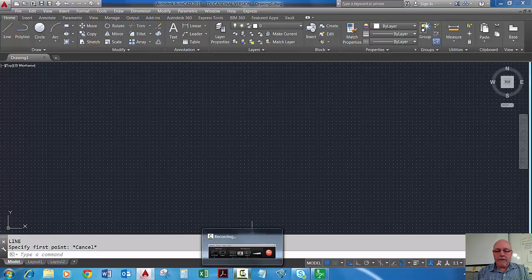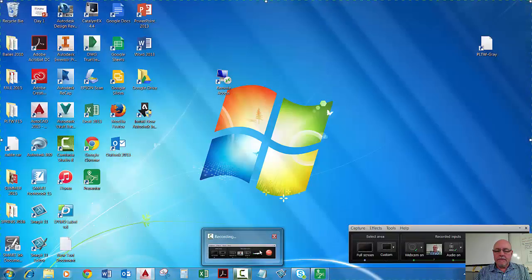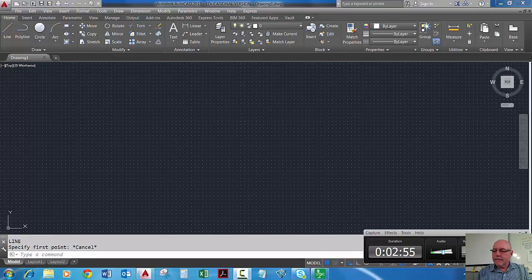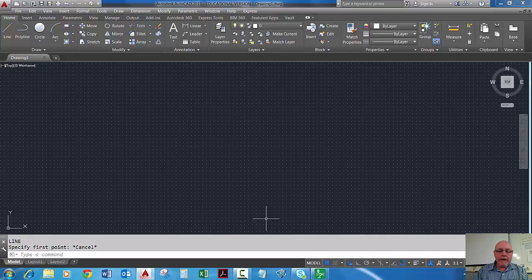I'm going to pause for just a moment. So you'll find the use of the dynamic input pretty handy. The book will take you through several steps, so follow those. Essentially, I'll just show you in using it. Don't really have anything else turned on. We'll turn off object snaps. I'll turn off annotation. And hardware acceleration is on. That's okay. And of course my grid is on.